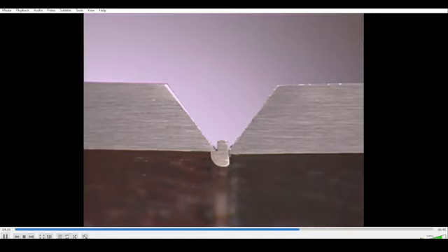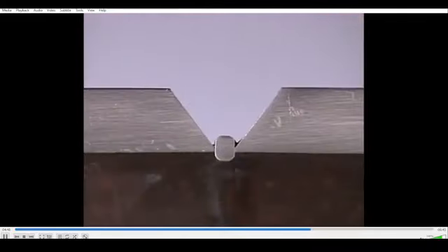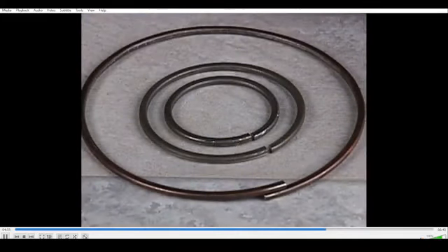Both the J and A inserts are available in coils, preformed rings with an overlap, or split-butted to allow for variations of the inside diameter of the pipe. The K-type insert, sometimes called a Grinnell ring, is produced by rolling wire into a flattened rectangular shape. It too is available in similar forms as the inserts already mentioned. Rings having a diameter up to 2 inches are not prepared with an overlap. Inserts over 2 inches in diameter are prepared with some extra diameter to allow for variations in the inside diameters of the pipe. The overlap can be cut off with a saw or hand shears.